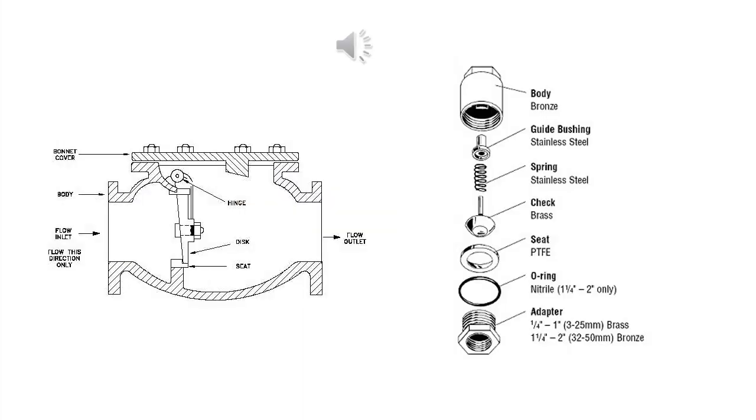Check valves are flow sensitive and rely on the line fluid to open and close. The internal disc allows flow to pass forward, which opens the valve. The disc begins closing the valve as forward flow decreases or is reversed, depending on the design. They will have an arrow imprinted on the body of the valve showing the direction of flow.